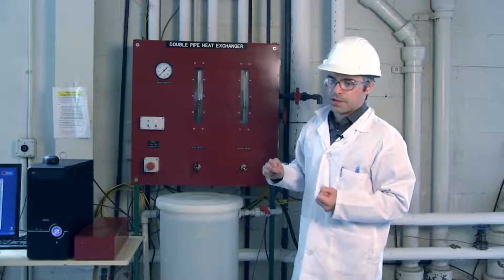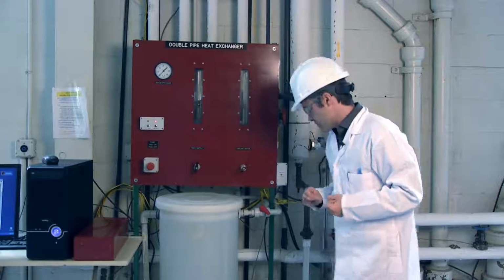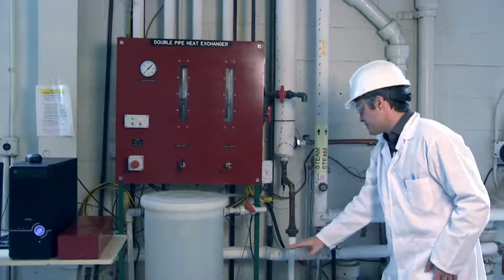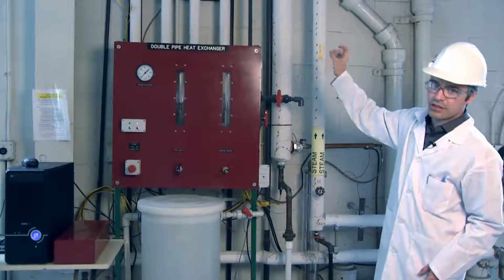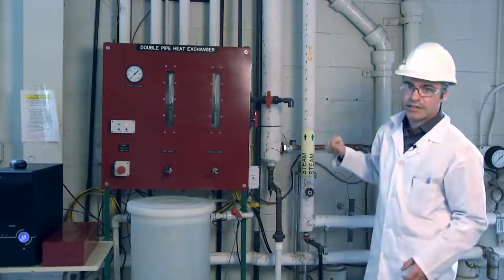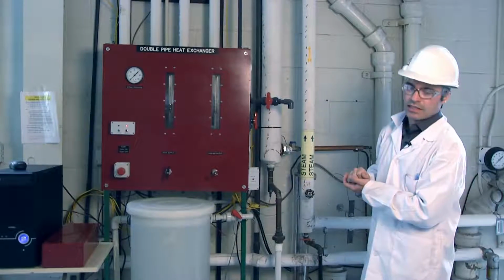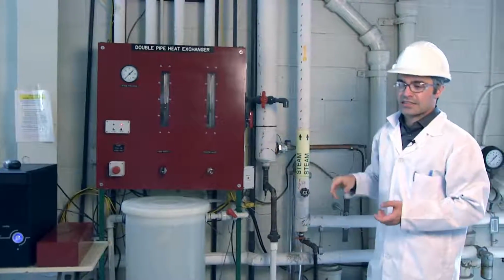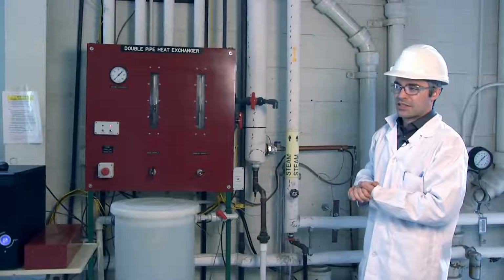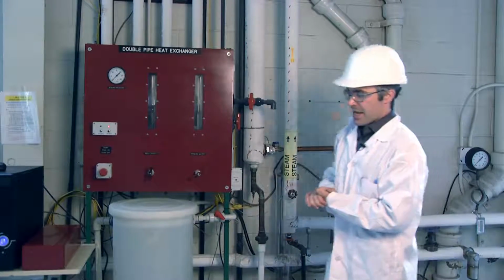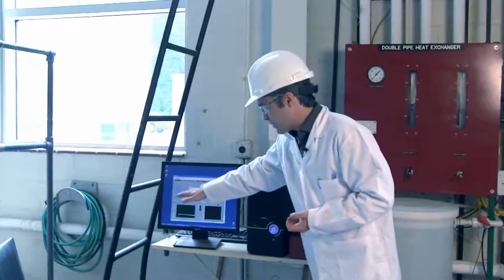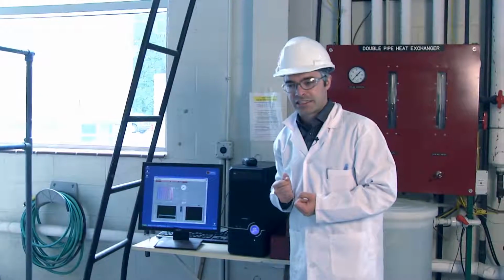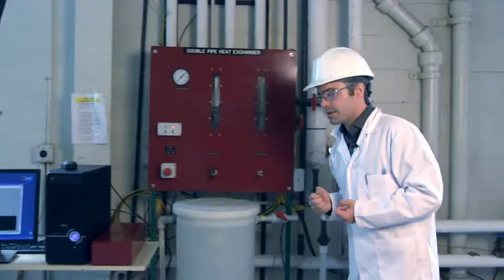You must, at minimum, calculate the residence time of the water throughout the entire system, depending on your feed supply rate. You know you're working with approximately inch-long pipes. You have just over 2-meter sized pipes. You have 5 of them. How long is it going to take for 2 gallons of water to reside throughout the entire system? This is the minimum amount of time that you'd have to wait for equilibrium to become established. And once all the temperatures have stopped changing for a period of time, you can then believe you're in equilibrium and begin collecting the data for your experiment.